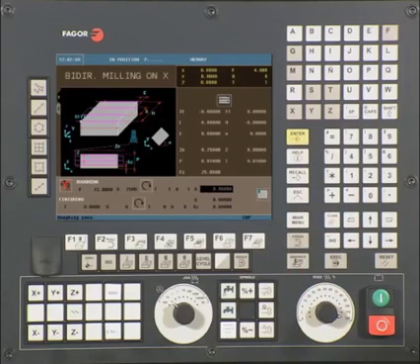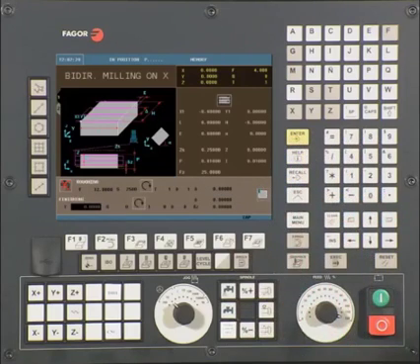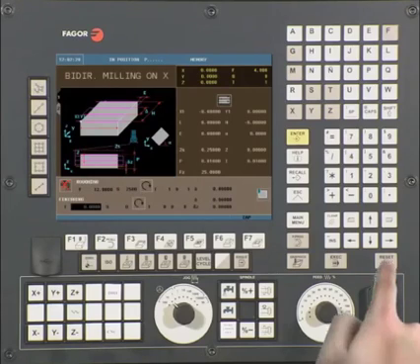Next is your milling step-over field. To ensure clean cuts, type in a value less than the diameter of your selected tool. In this example, we are using 0.8 inches. Type 0.8 and press Enter to continue. In this example, we will not define a finish operation. It will be necessary to set the finish tool number and offset to 0 to skip this operation.